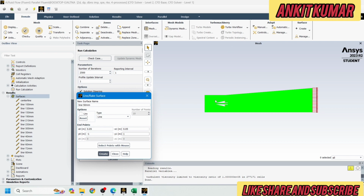Our combustor height is 50 mm. If I write -1 meter to 1 meter, it will be a very long distance, so it will automatically cover the combustor's y distance, whatever its height is. The x value I have written as 50 mm. Our axis is here in the center, so it will go to 50 mm somewhere here and make a vertical line at 50 mm covering from here to here. Now click on create. So the 50 mm line will be created.